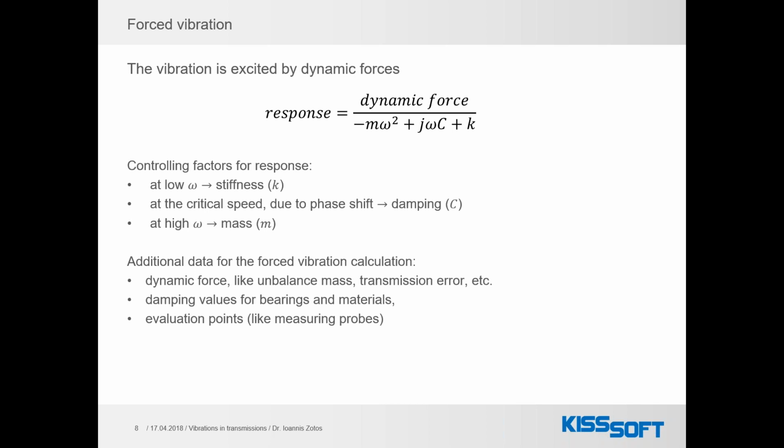So we can have a quantitative, qualitative way of describing how the response is changing for every frequency range. In order to calculate the dynamic response, we need some additional data. These are, of course, the dynamic forces that are used to excite the structure. This can be an unbalanced mass or a transmission error in a gear pair or any other thing like that. We are going to see dynamic forces, excitation forces later on in this presentation.